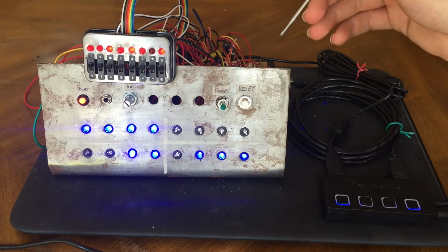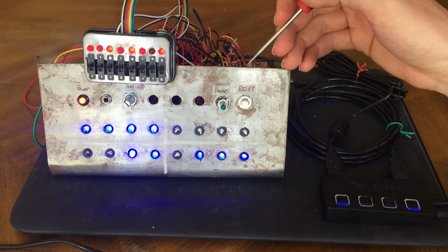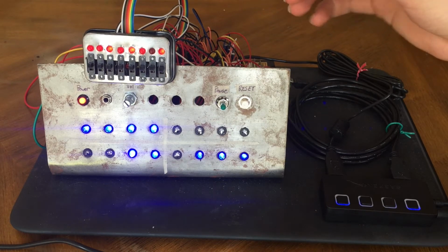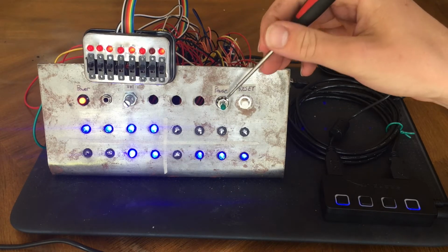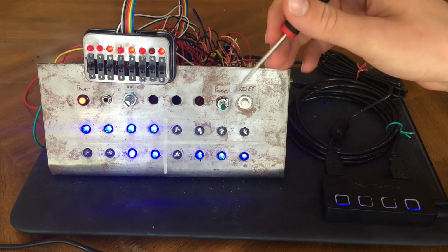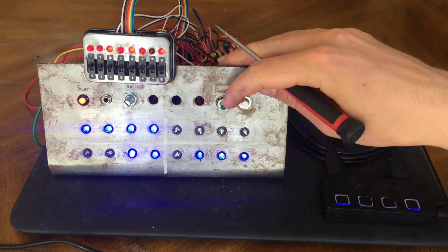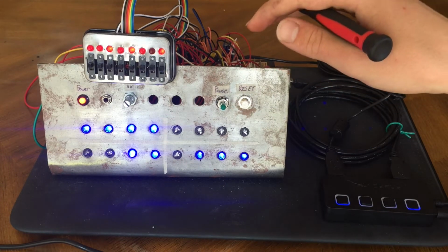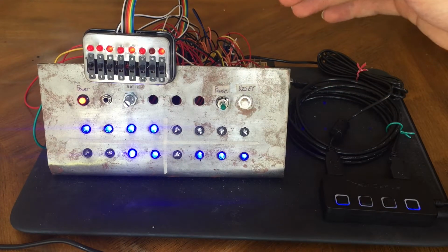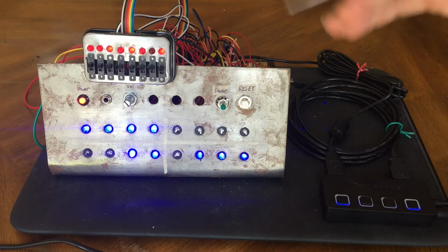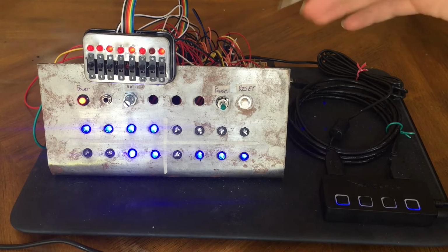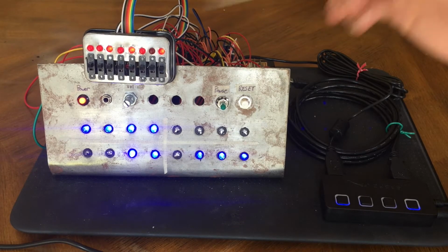Right now the computer's running at 1 megahertz, but initially I was running at around 5 hertz. So having this on there in that initial testing was really useful because I could just pause the processor whenever I wanted, take a look at the lights and check, okay, is this in the right location and is it executing the code correctly?